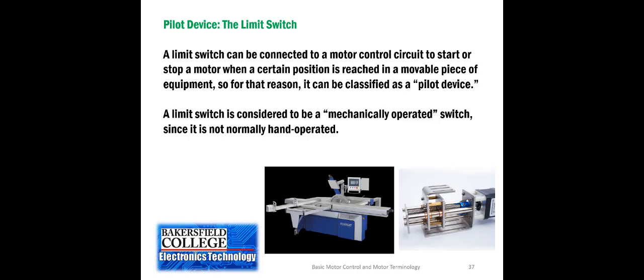That selector switch will override what the controller tells the machine to do, and when it hits that limit, it stops moving, and that keeps the mechanisms from being destroyed if the movement is blocked or stalled. Now, what you'll see on the right-hand side is a movable surface that moves back and forth as the motor rotates. It has a screw, a lead screw, that moves it back and forth.